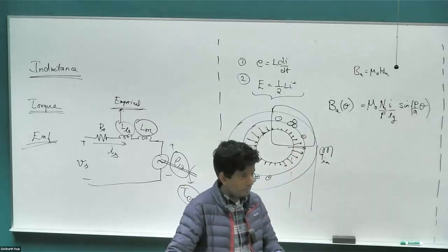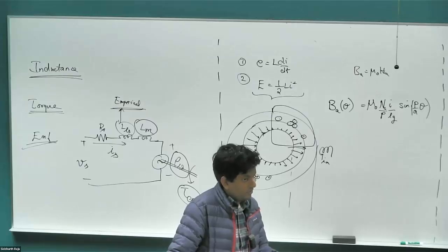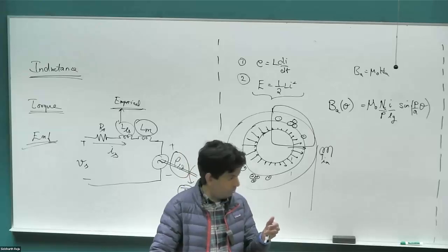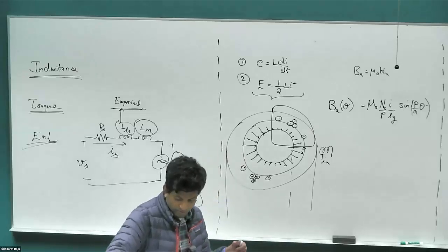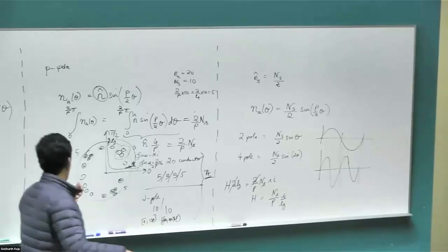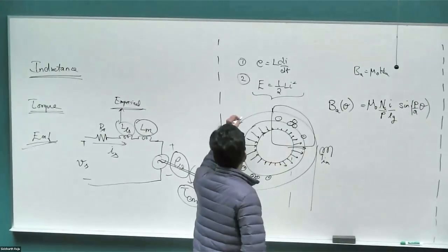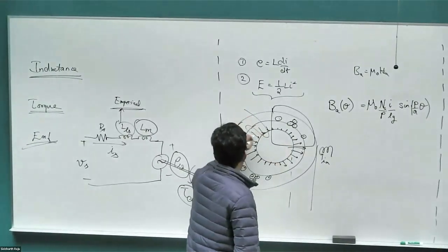Do we always count the 2 air gaps, like as you go out and come back in? Yep. Okay. Yeah, it depends on the path, however you choose the path. So the way I've chosen the path, we have 2 air gaps, but you can choose quite an odd pathway that goes through the air gap multiple times. There is no restriction on what the loop needs to be. So you can choose a loop that looks like this.